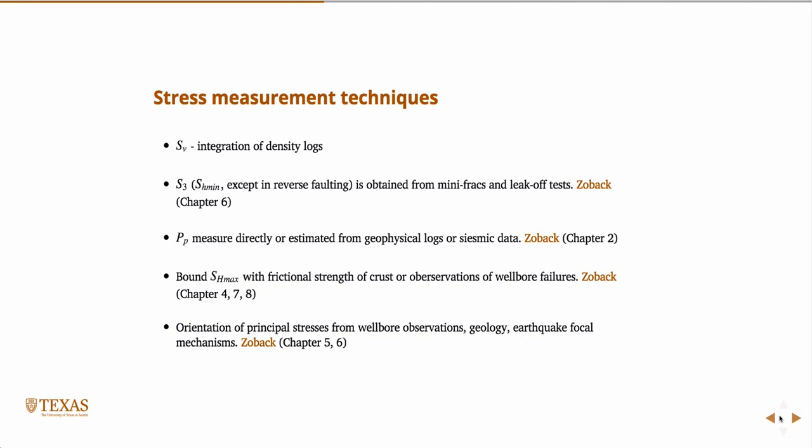But you can have small breakouts along the wellbore, and we can use our knowledge of the stress state around the wellbore to help us determine what direction those breakouts occur at. Well, they commonly occur in pairs along the side of the wellbore, and it turns out we'll see that corresponds to one of the principal stress directions. And so we can use that information to help us determine it.